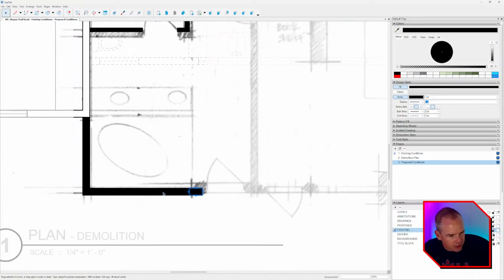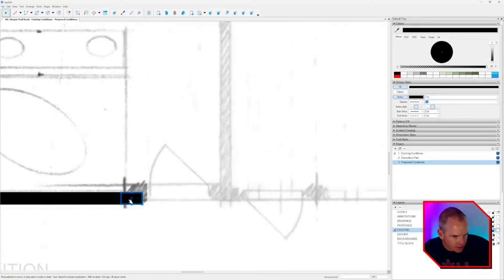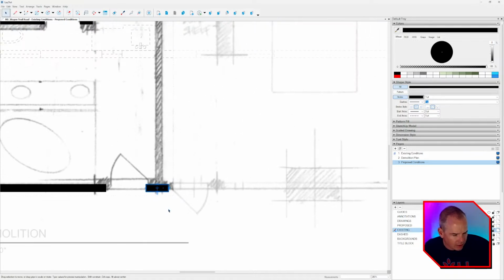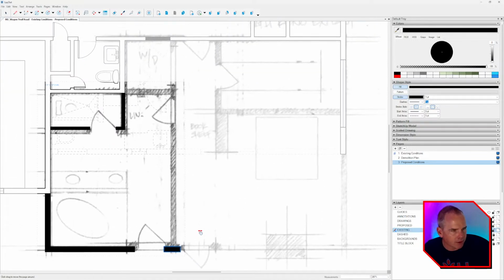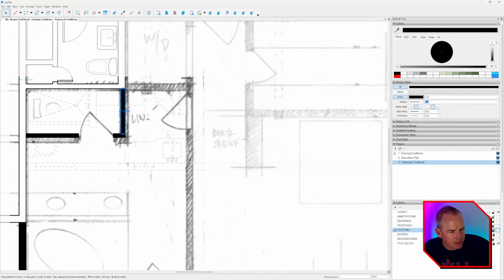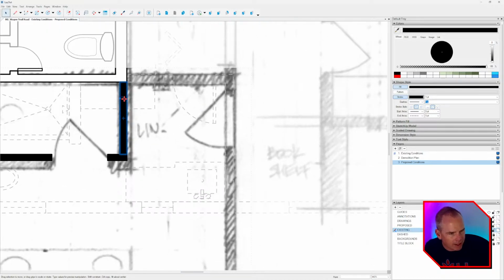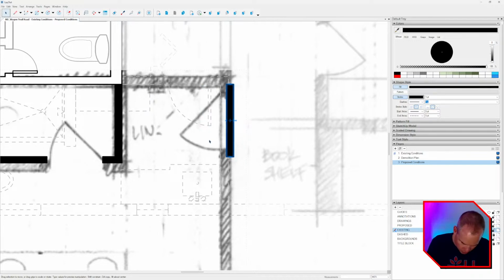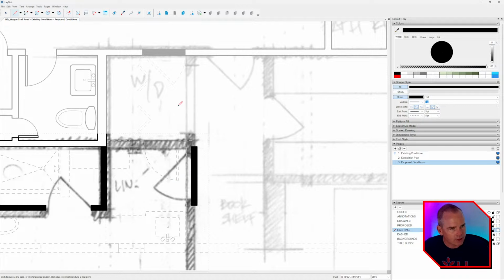I guess what I'm doing is I'm just keeping an eye on my sketch, but typing in some clean dimensions, like -3 feet, enter, and then kind of flip it. All right, so over here now, I might make a copy of this to here, and then if I shift an arrow, 1, 2, 3, 4, 5, shift arrow key gives me a 1/4 inch nudge. So now we're up at 60 inches in there, and that's probably about right.